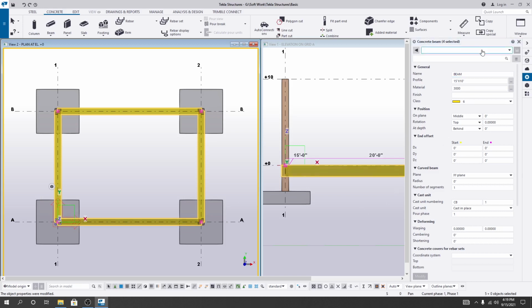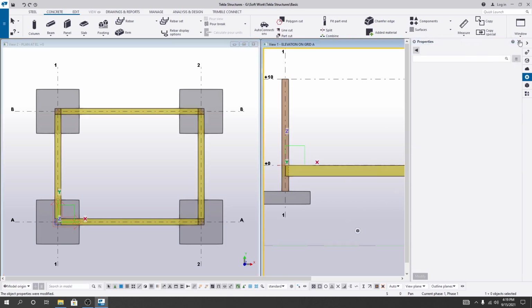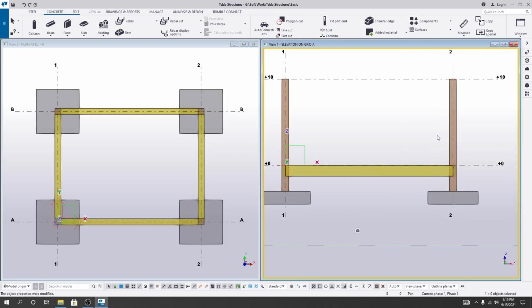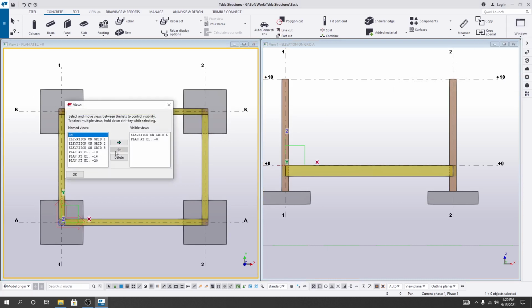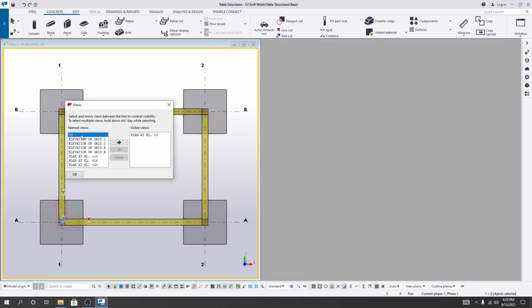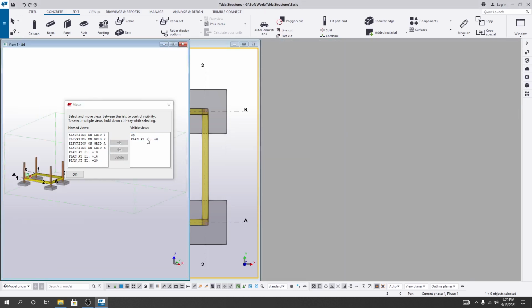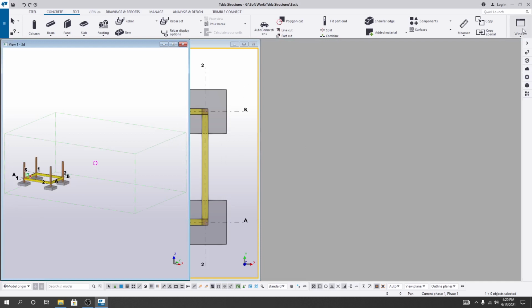Clear? Now what I'll do actually, I'll close it. So just see, we have created, and I can go view list, and from here I'll just remove that one and I'll take 3D. Okay, and I'll click OK, and from here I'll take tilt vertically.